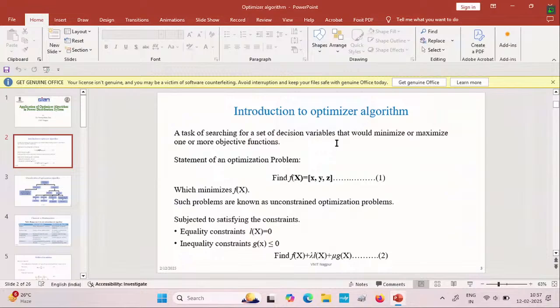At that time, our P demand and Q demand for that specific node will change. The moment we place a DG or any renewable energy source on that node, we consider it as a PV bus, and it is feeding power to that particular node. Based on that, our calculation is again carried out.